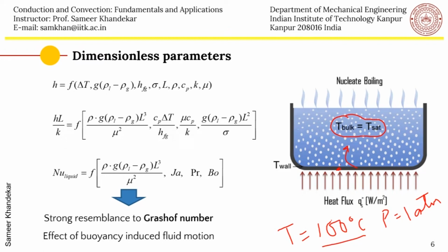Then the bubbles are formed. Bubbles are lighter than the bulk liquid, so naturally the density of the vapor is lower, and the bubbles will tend to rise upwards. So there is a buoyancy force, g delta rho, which is affecting the process. Then there is a latent heat because phase change is happening. If you recall our pressure enthalpy diagram, this is the pressure, this is the enthalpy, and the saturated liquid is getting converted to saturated vapor.